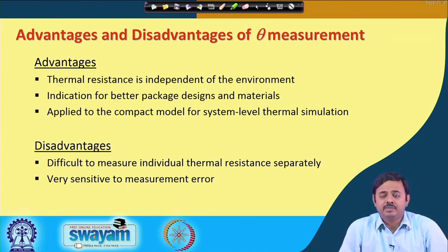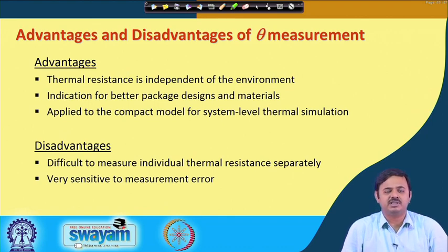So, sometimes theta can be calculated, sometimes theta is measured. You know how much power you are putting in, and then you measure the temperatures and determine what is theta. The advantage is thermal resistance is independent of environment. It does not depend on the temperature.